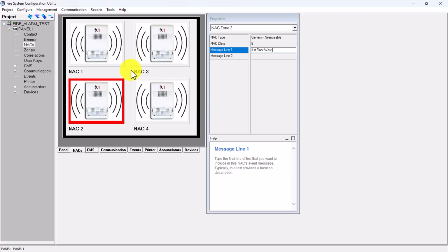But when you have the supervisory latching and non-latching, same as the relay silence and relay silence latching and non-latching, if it's supervisory latching and a sprinkler tamper goes into supervisory, you will have to physically reset the system once that supervisory is clear in order to reset that trouble signal or that supervisory signal on the fire alarm control panel. We usually put non-latching, so once it clears, it resets itself automatically.